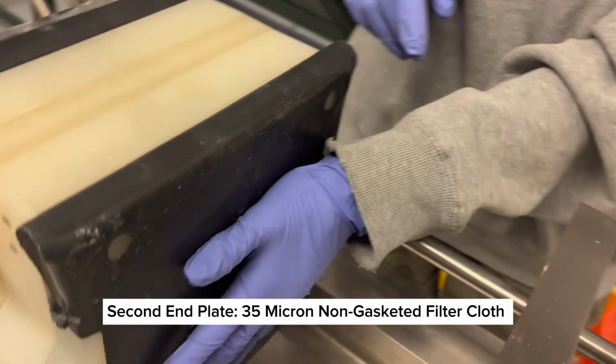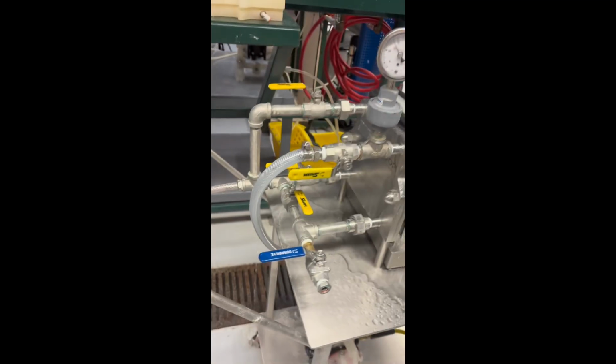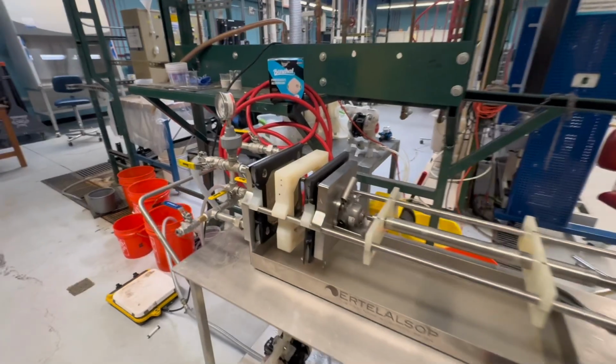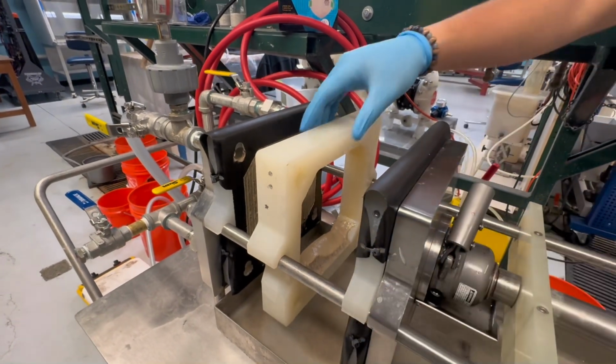Once the slurry passes through the end plate, solids are separated by the filter media, and liquid passes back through each chamber and gathers at the outlet hose where filtrate is collected. Separated solids gather within the filtration chambers and begin to form a filter cake.